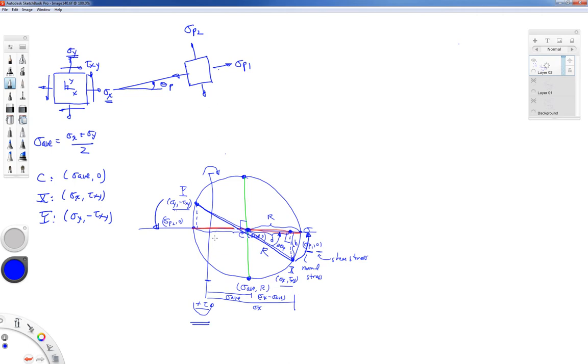All right, so now we're on the red diameter, right here, the horizontal, and we want to get to the maximum shearing stress state. We have a couple choices we can make. We can continue on and click ourselves in from the red diameter into the green diameter position, or we can back it up and go clockwise from the red through our original position to the green diameter. Let's back it up and go the other way.